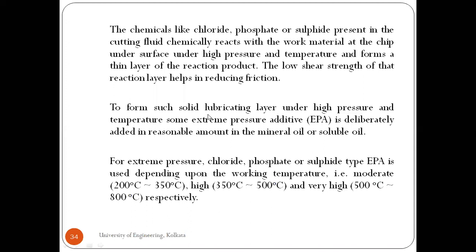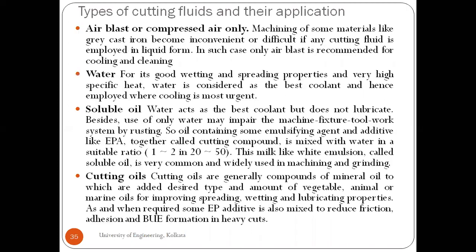As I also told you, solid lubricants are also available. However, we can also use some mineral oil and some soluble oil as lubricants. So for extreme pressure, chloride, phosphate, or sulfide type extreme pressure additive can be used. And for types of cutting fluid, we'll quickly go through this.